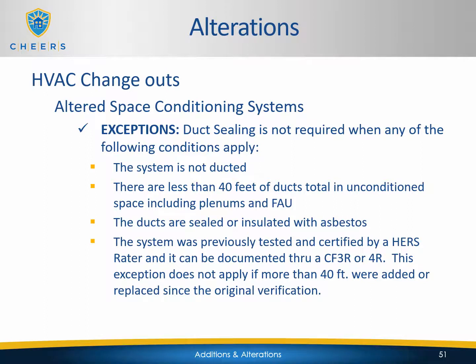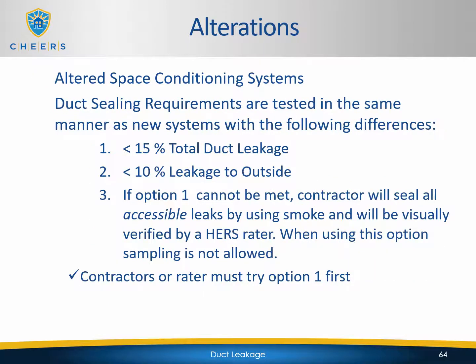And please keep in mind this is only applicable to altered space conditioning systems. An altered space conditioning system is going to be tested in the same way as a new system would be, with a couple of differences. You're still going to perform the total duct leakage test exactly the same. You're going to perform the leakage to outside test exactly the same. The only differences that we see here is in the pass-fail criteria.